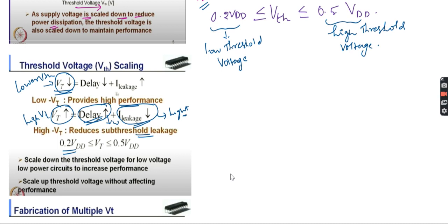So how will they set the threshold voltage? By adjusting the doping concentration levels. After putting in the substrate and the diffusion, the doping concentration they choose fixes the threshold voltage, right? So they need to fix it for two different circuits with two different threshold voltages.